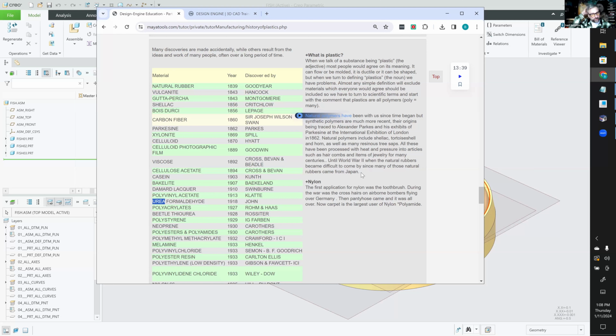Another really good question that one might ask in a job interview is what's a good draft angle to put on a part? And if you have this sort of confidence, your answer would be, well, it depends on what texture you put on the part. If you don't have the right confidence, you're just going to say 1 or 2 degrees, right? But the question merits a question. So if you ask that question, your resume is probably going to go into the let's hire this guy pile.